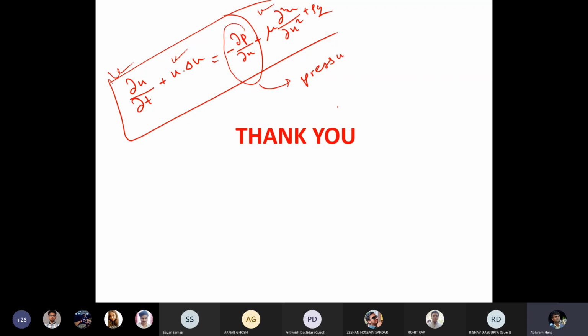Pressure and velocities are coupled, they are related, and that's why individually you cannot do it. You need to take the help of del dot u equals 0, that is the continuity equation. So this pressure and velocity coupling will be done with the help of the continuity equation. That makes the thing a little bit difficult, that's why people struggle a little bit with understanding. We'll try to understand this particular part in as simple a manner as possible, and that will mark the end of this course.